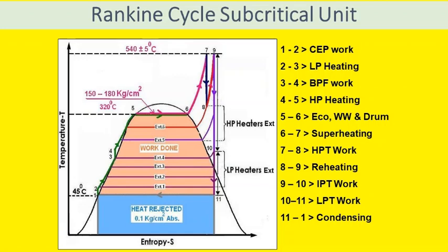So 8 to 9 represents resuperheating or reheating in the boiler. Though you see the pressure of reheating is less than the pressure of superheating, so naturally the degree of superheat is more in the case of reheating. After reheating, we have expansion in the intermediate pressure turbine, that is the IP turbine, 9 to 10, and 10 to 11 is the expansion in the LP turbine.